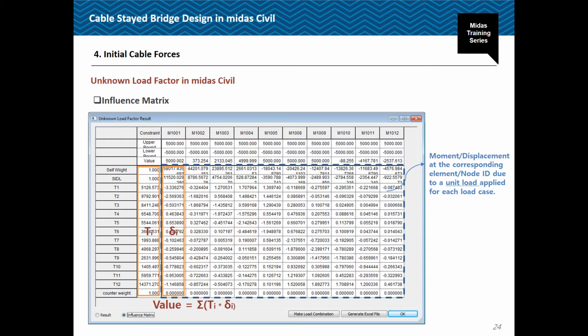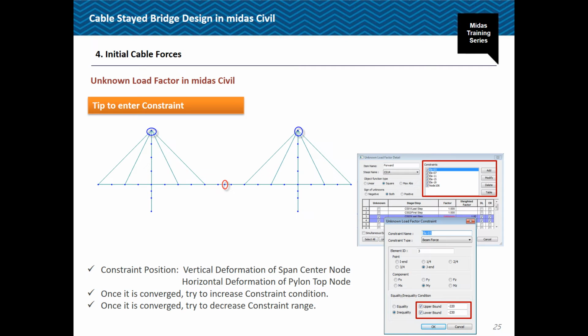So what the software does, it produces what's called the influence matrix for the cable, which is something very similar to what would be the influence analysis for moving load analysis. The table is actually drawn showing what's the influence line for one cable at a time, and the solution is found using this matrix. Obviously, if you had to do this by hand, it would take a lot of time, and there's not going to be too much value in doing it by hand, honestly.